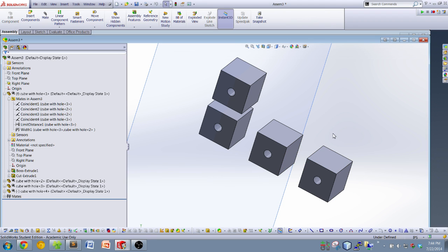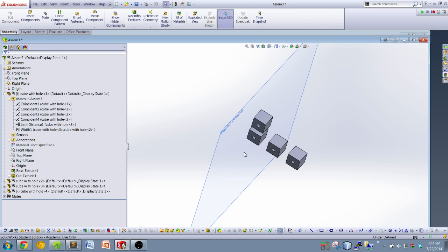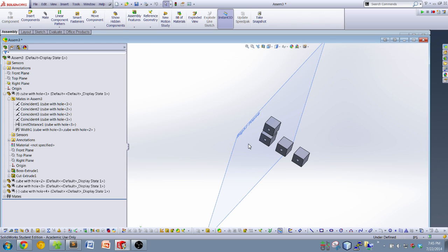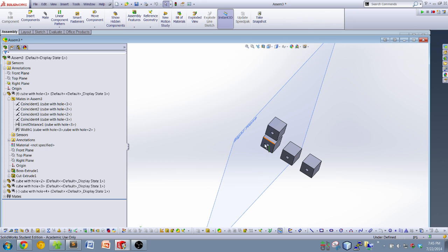If I rebuild, right now everything's fine because it's a relatively small thing. But on occasion, and it happens a lot when you do electronics layout, when you start getting tons and tons of mates, it can't keep up with solving. I'll move a hole and there'll be a Talon over on the left somewhere that's no longer at that hole even though it's mated to it. You hit rebuild and it'll move everything back over, resolve all the mates, and make things right.